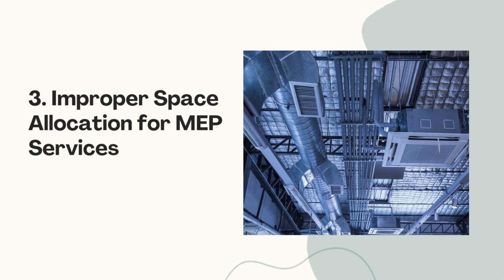During the design stage itself, allocate proper space using clash detection tools. Cross check with architectural and structural drawings early on and always define the mounting heights clearly in coordination layouts. All mounting heights should be mutually agreed with the clients and vendors or with the design consultants before the execution of works.